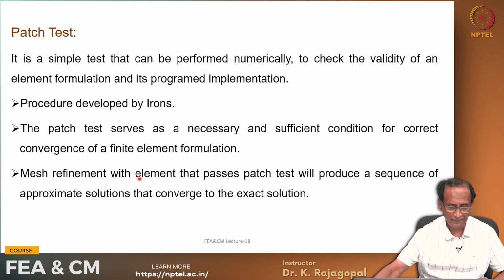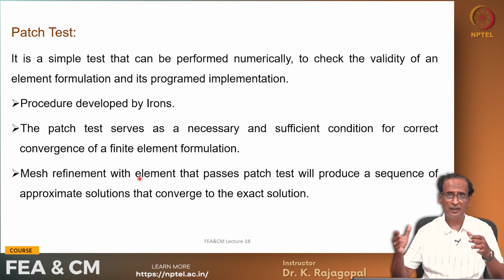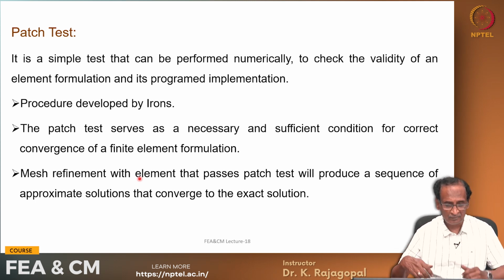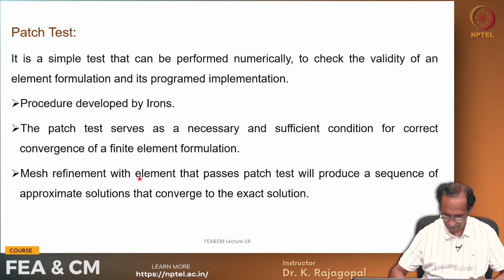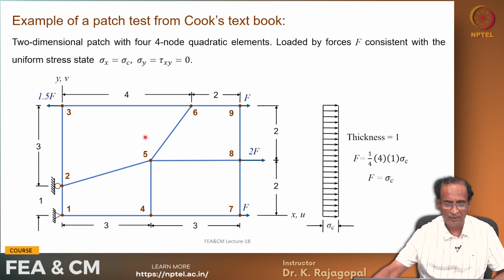And sometimes a mesh may not pass the patch test, but as you make the mesh more and more finer, you might pass the patch test. That is also acceptable. And this particular example I have taken from Cook's textbook.